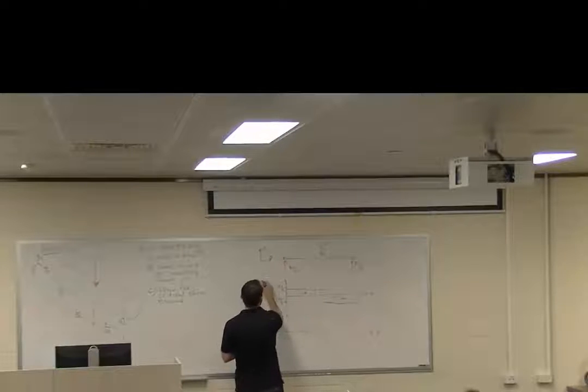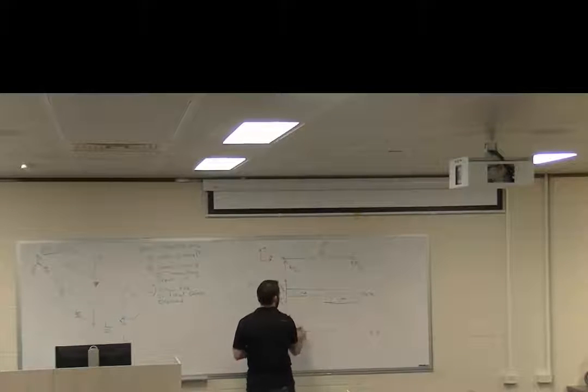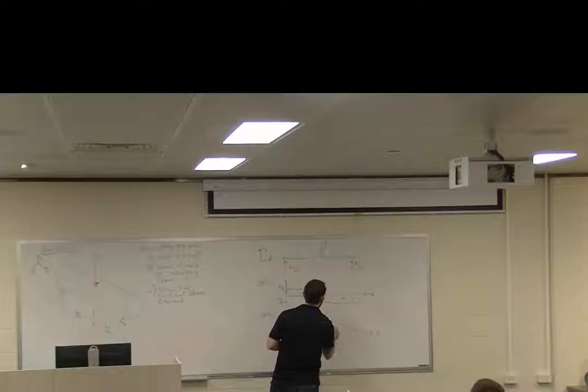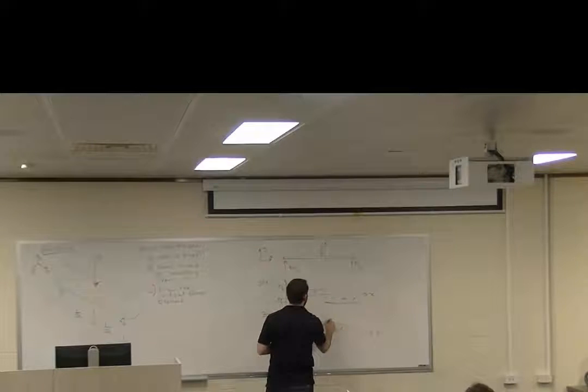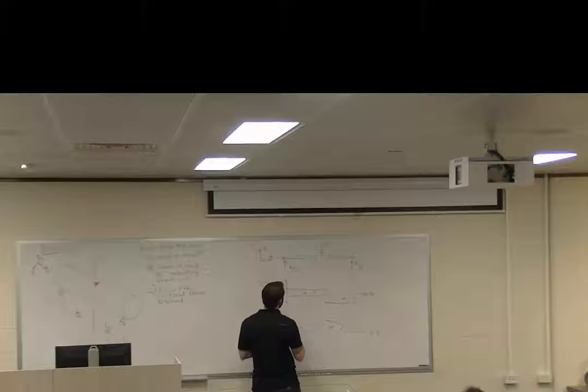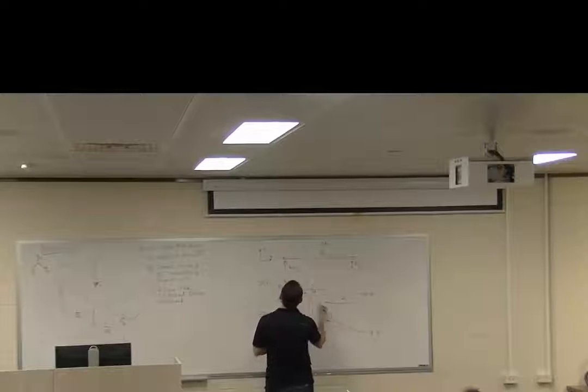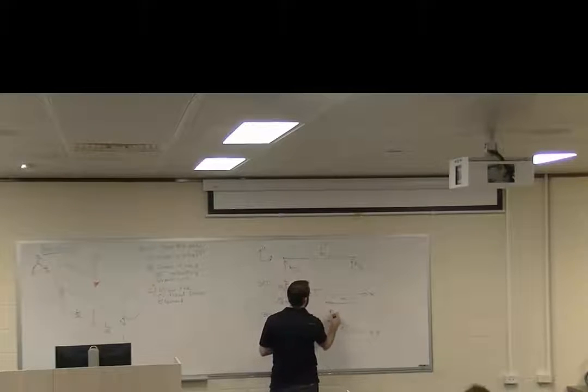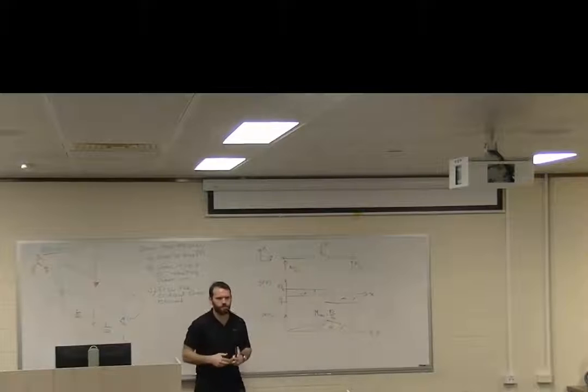And that our, let's say, shear force diagram, bending moment diagram, and our bending moment goes up to a max and down. And if you wanted to determine that max, what is that? FL on 4. Yep, so everyone got that?